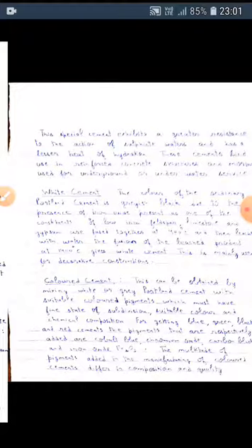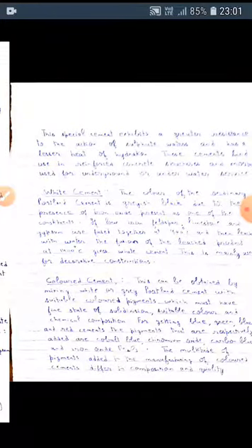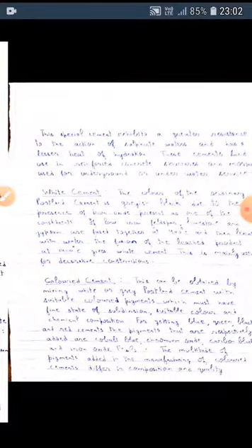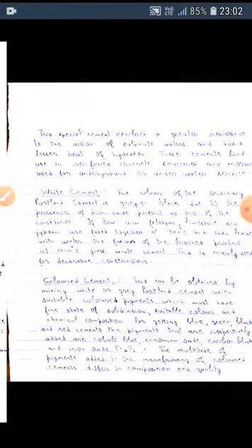Colored cement. Colored cement can be obtained by mixing white or grey Portland cement with suitable colored pigments. These pigments must have fine state of subdivision, suitable color and chemical composition, not destroyed by the components of the cement. For getting blue, green, black, and red cements, the pigments that are respectively added are cobalt blue or ultramarine, chromium oxide, carbon black, and iron oxide. Pigments of mineral as well as organic origin are available.